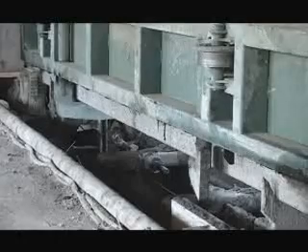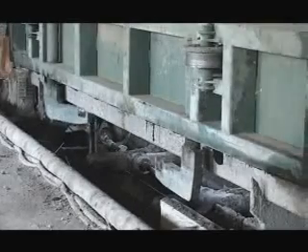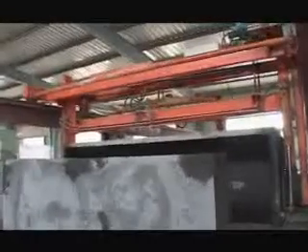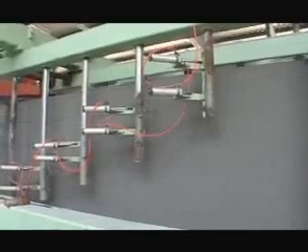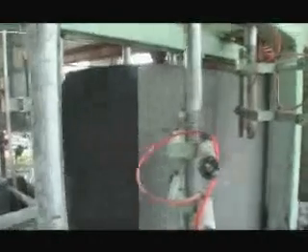Then open the mold by the overturn hoist manipulator automatically and leaves the cake together with the side plate tilting on the cutting trolley. The demolded cake is cut in fixed points step by step. Firstly, the cake and the trolley is cut horizontally by horizontal cutter. This process is finished by a cutter blade and steel wire tightened by air cylinder.